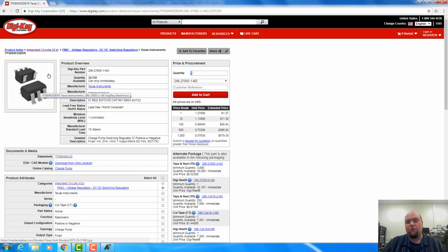So you can think of it as you charge. This is fairly easy to think about. You could do this just manually. You take a capacitor, you hook it up across the terminals of a 5-volt supply, and then you disconnect the capacitor and move the high potential side of the capacitor to the ground reference. Well, now the low potential side of the capacitor will be a negative 5-volt signal. That's what a charge pump, in this case an inverting charge pump regulator, does. It just uses a collection of FETs to do this sort of switching with the capacitor.